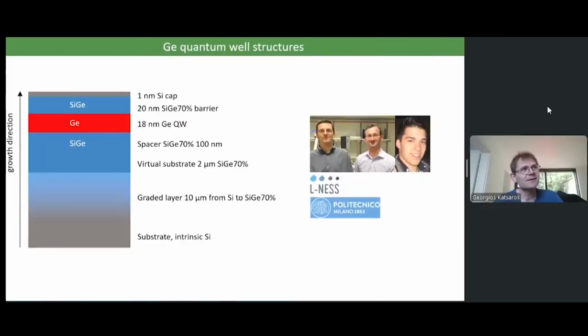A related question was, I'm assuming that ohmics is just putting down some metal, nothing else. Yes. Also there we are lucky. We do a soft ion milling, and then we put platinum, which has a very high work function, which for holes is what you want. Yeah.